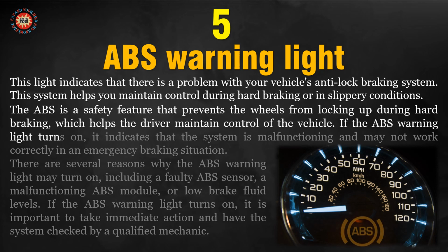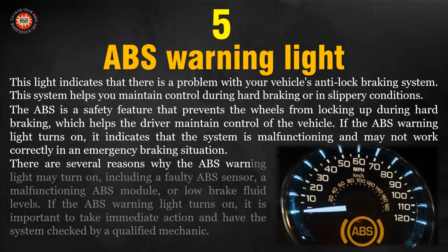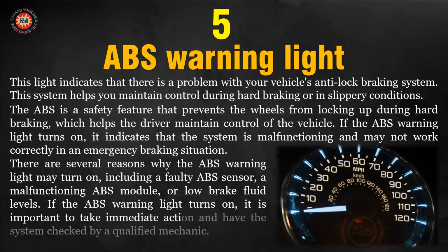If the ABS warning light turns on, it indicates that the system is malfunctioning and may not work correctly in an emergency braking situation. There are several reasons why the ABS warning light may turn on, including a faulty ABS sensor, a malfunctioning ABS module, or low brake fluid levels. If the ABS warning light turns on, it is important to take immediate action and have the system checked by a qualified mechanic.